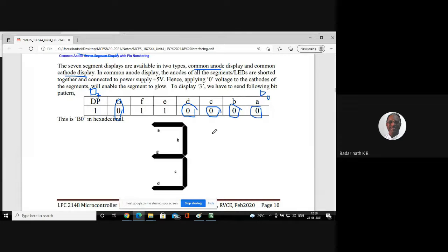Now let's go to the interfacing design. First we have to understand the concept. What does concept mean? It is the behavior of the peripheral you are interfacing. In interfacing, 3 steps are there: understand the peripheral, then build the circuit design, then build the program. So now I've understood the peripheral, how the 7 segment digit is available in the market, which one I have to purchase, and what the pins of the 7 segment digit are. Now I'll start the second aspect of my product development: interfacing.